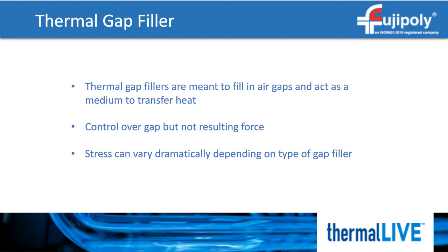This means actual stress created during the compression can vary, and in most cases can be higher than desired. Gap fillers are typically not used in applications with a fixed force like a spring-loaded heatsink. They are used in applications where there is a gap. The gap is controlled, and there is some tolerance based on the component and assembly tolerances. The actual load or stresses are dependent on the actual gap filler used, specifically the starting thickness.